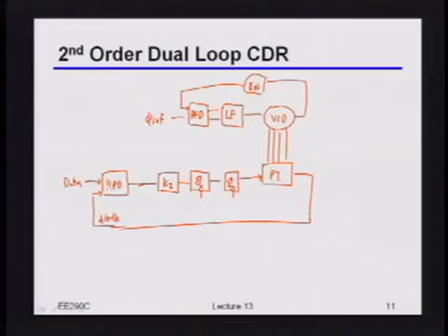Okay, so now if I'm really building the equivalent of a PLL, or actually just in general, will what I just drew here work, or will this have a problem? Yeah, it's unstable, right? I just put two integrations in the loop with no stabilization, no zero, no nothing, right? So how do I add the zero in?